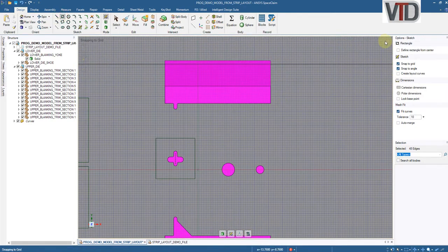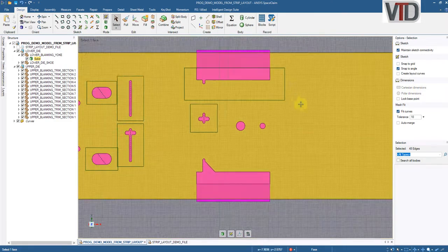So I'm going to go ahead and do a rectangle. Now this one I don't want to do a rectangle from center, so I'm basically going to go to a point and press and release the shift key, and now I can track from a point. So I'll go maybe 1.25, and now I can start my rectangle there. And in this case here, I know I want to be about 1.5 from this edge, so I'm going to do the same thing from here, and I'm going to go minus 1.5, and I'm going to go about 2 inches there. That dimension's not as critical for me.